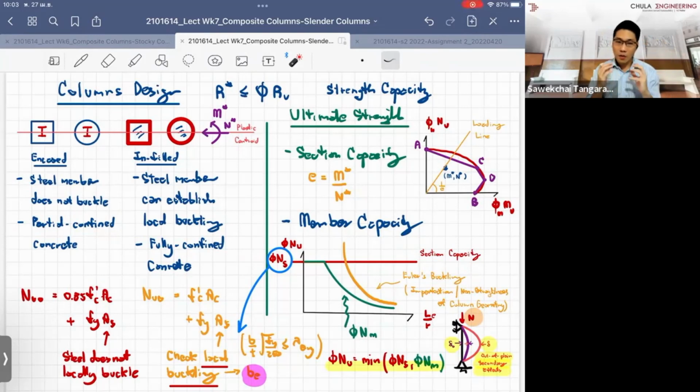So we go back and think about what we have done in the last 6 to 7 weeks. We start from the strain and we look for the stress. We transform the stress distributed to each of the materials by taking the areas underneath the stress, transforming them to be the force applied to the centroid of the stress diagrams, which gives you the force, and then you calculate the bending.